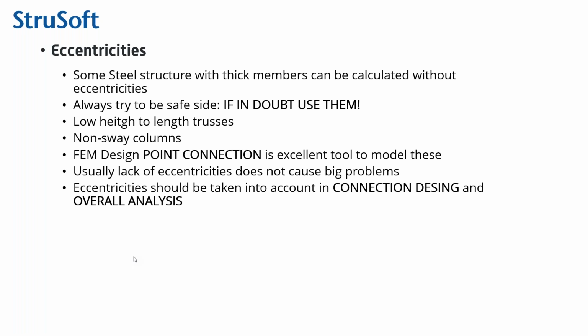There's a question. If the beam model is selected, is it possible to consider the local buckling in FEM-Design? We will take into account the local buckling, the shear buckling, and of course the cross-section classification is taken into account, the buckling in lengthwise forces. But we don't have any local force checks in FEM-Design. But it's easy to also put some stiffness in the location of the high loads.